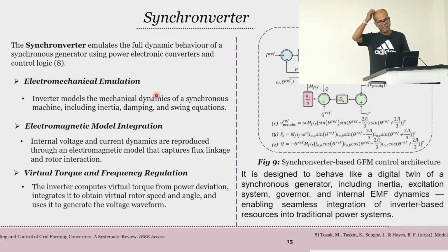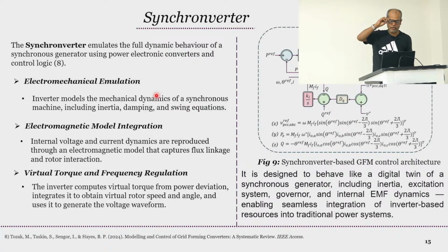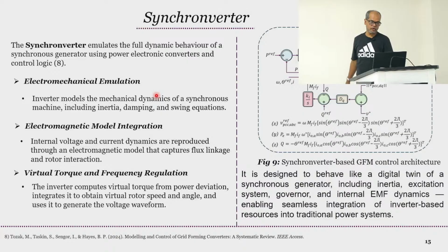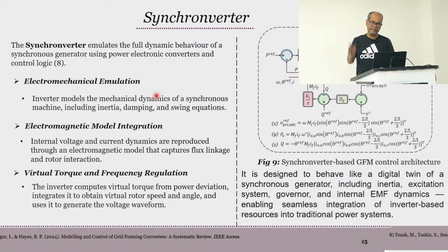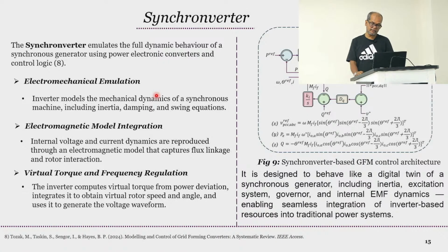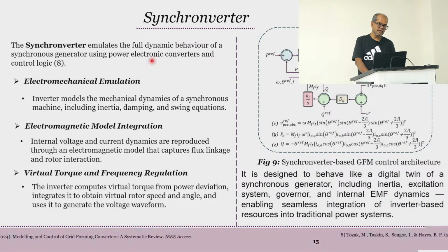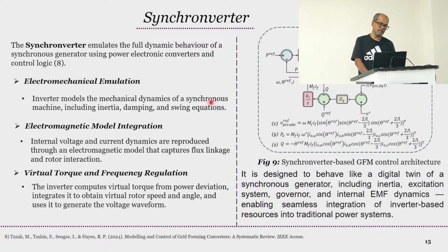The one that I mentioned, the synchroconverter, exactly emulates the full dynamic behavior, not only the swing equation. If you remember, VSG only takes the swing equation, but this one tries to emulate the full dynamic behavior of the synchronous generator using the power electronic converter and the control logic. That's the biggest difference.